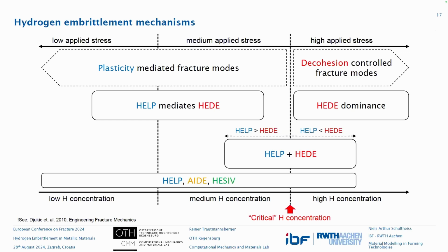The other one is AIDE. The idea is that it promotes dislocation emission on the surface, so it eases the hydrogen uptake in areas of hydrostatic stress. And on the other side, for high applied stress or high concentrations, we have the HEDE mechanism, which is associated with a sudden catastrophic failure, a decohesion, and a very rapid loss in ductility.